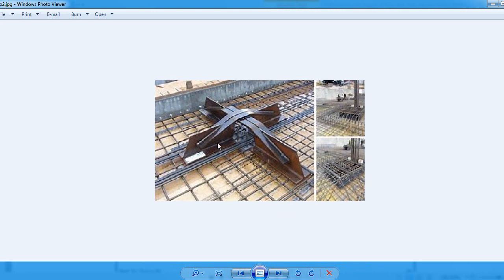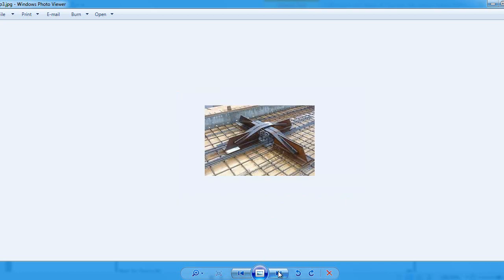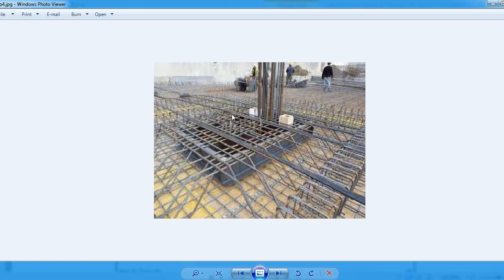This is very important: a steel I beam, W shape or S shape beam, is provided at the column place, and a greater amount of shear capacity of the concrete can be achieved. And remember, it also plays its role in negative flexure as well. It also controls your flexure. And the next one is also an arrangement. You see the column in the middle, and these I beams are provided, and these bent up bars you see in different locations. They provide bent up bars here and here, so that the purpose of this is to control the crack.